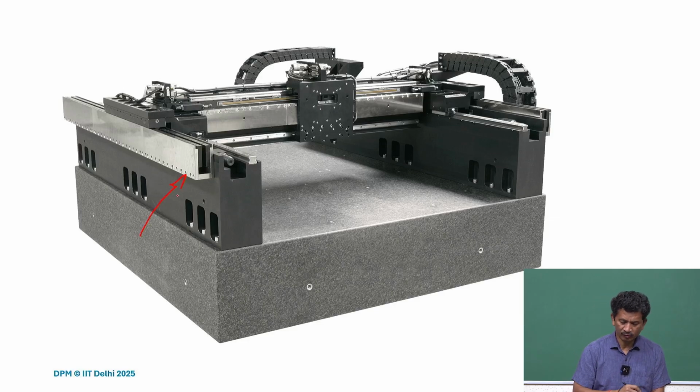Yes, linear motors are used in other applications, but what you realize is that in this case you are still using these linear guides, which are friction based. So of course, depending on the application, it can be done. You can match it and use it. So again, direct drive, but then you have the linear guides. You can also notice the linear encoders here, so you can get the position feedback.